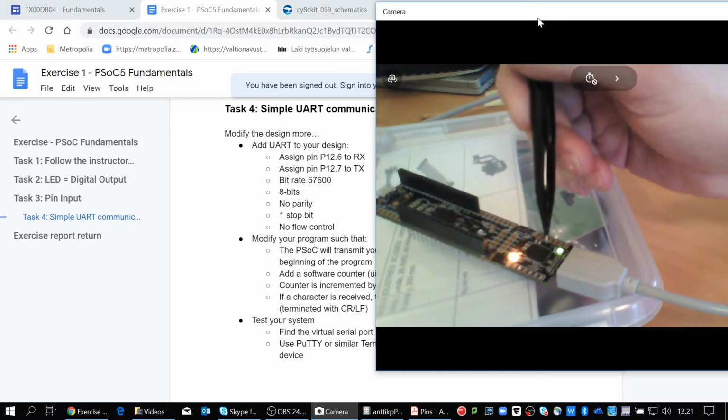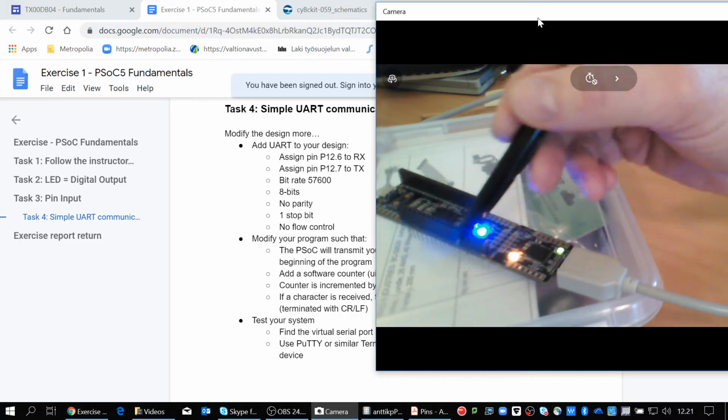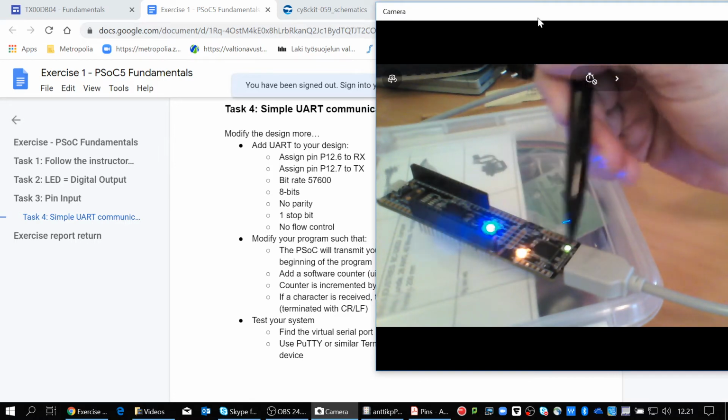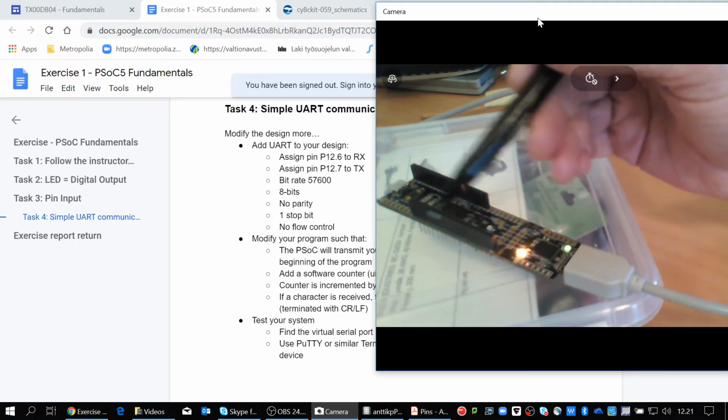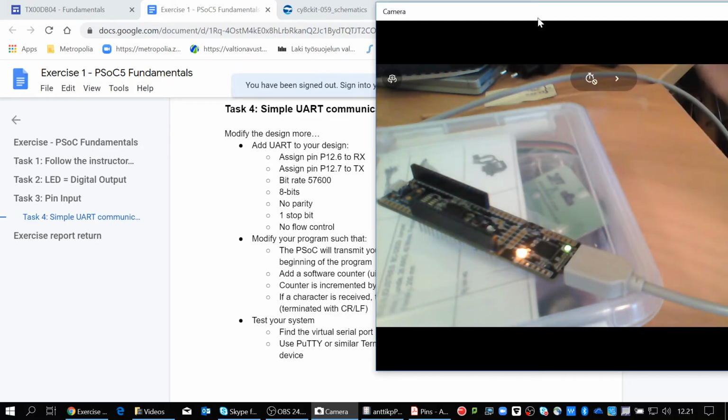So practically now this device looks like a COM port, and it communicates directly with this UART. Okay, sorry, it might be a little bit confusing, but you probably got the idea. Anyways, whatever you send from this device as a UART will just be repeated as it is on the USB UART bridge, as long as you have the same parameters on both ends.